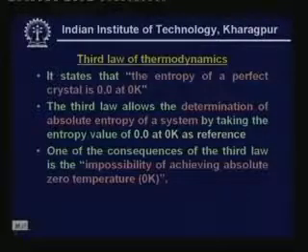I forgot to mention one thing here. I have given the expressions for Carnot heat engine efficiency, Carnot refrigerator efficiency and Carnot heat pump efficiency, and we have seen that all these are functions of temperature, and the temperatures there must be absolute. That means you must use the absolute temperature scale there to obtain the efficiencies of the Carnot heat engine, refrigerator and heat pump. You cannot use degrees centigrade or degrees Fahrenheit. You must keep this in mind.